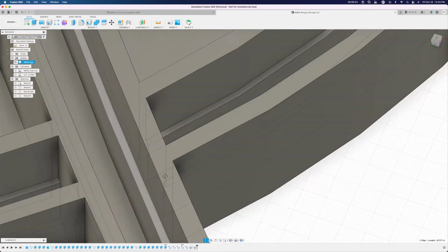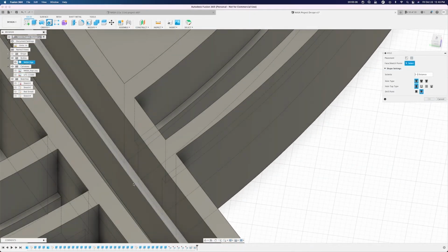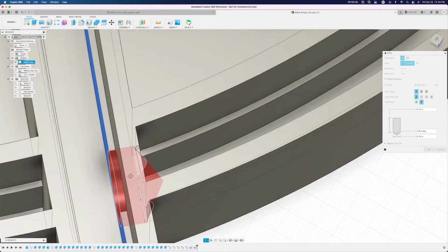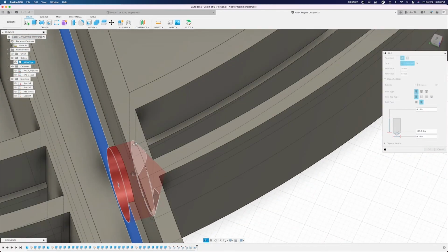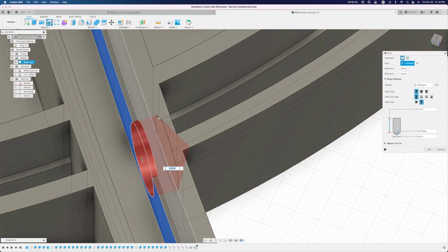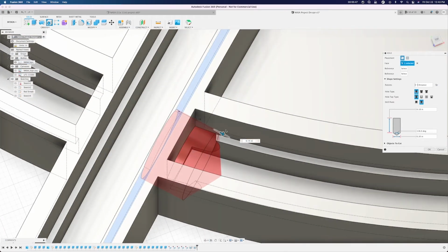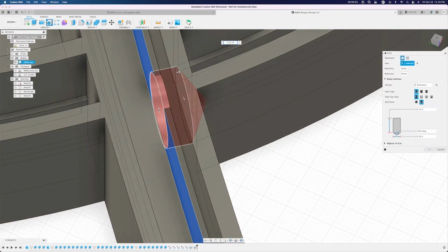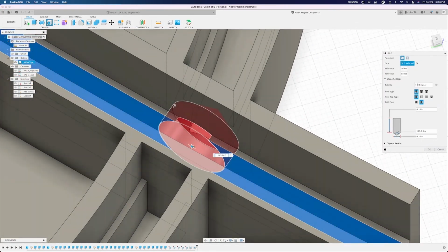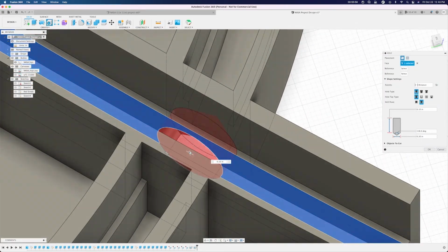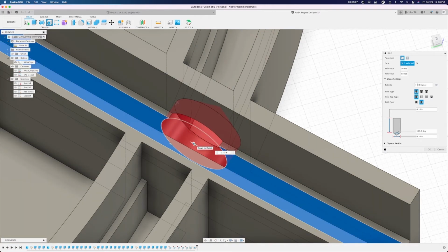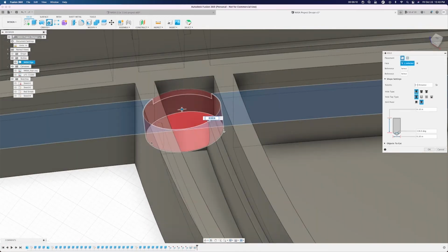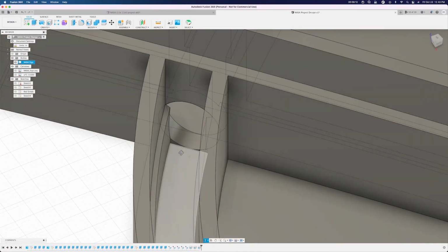Go ahead and zoom in. I'm gonna scroll to this side here, select hole, select here. It should automatically give you the option to extrude into the wall there, and it should automatically be a hole. Of course, you can make the adjustments here. I'm gonna go ahead and create a hole here, and adjust it accordingly. Make sure you're not going too low. As you can see, I can actually see the grid of my canvas. I just want it to hit just barely, but not actually touching the bottom floor of the design itself. And press enter. Now you see we have a hole here.